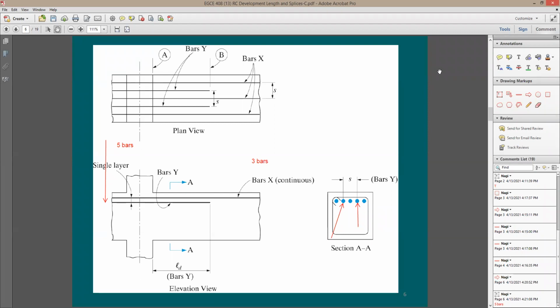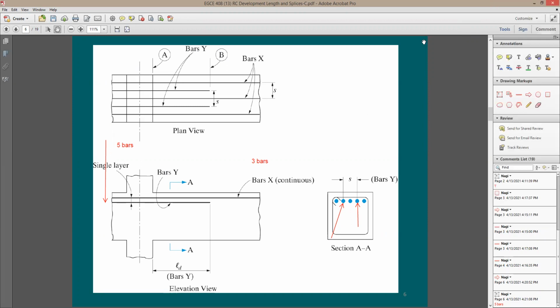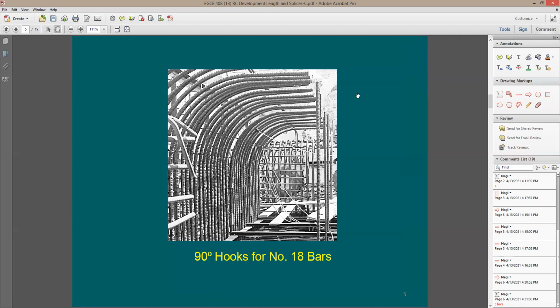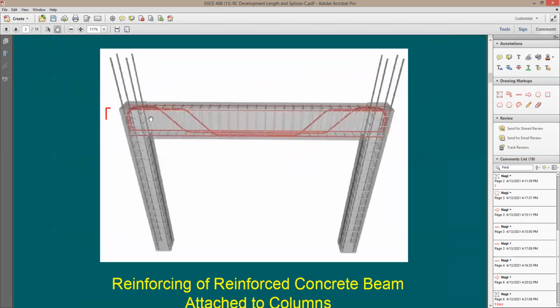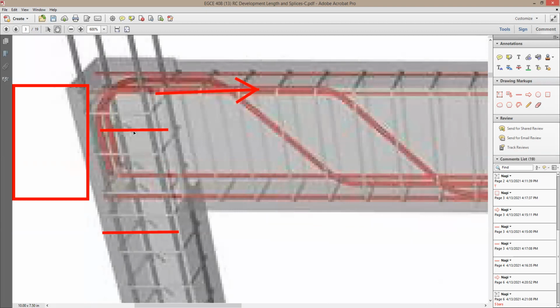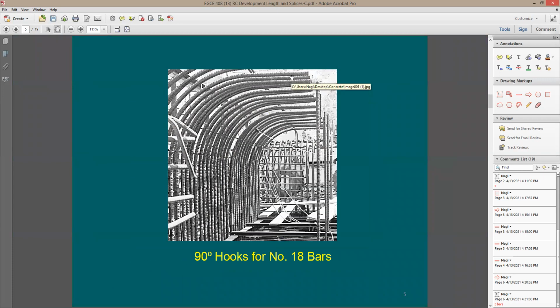The hook will be shorter. Why is that? Because the straight rebar relies only on friction and the connection to the concrete, whereas the hook pulls on the actual concrete. Okay, and in the hook you have some bearing, right? So in the hook you're going to have some end bearing when this hook is pushing against the concrete, and also you have the friction along this length. Good answer, Angel. Thank you.